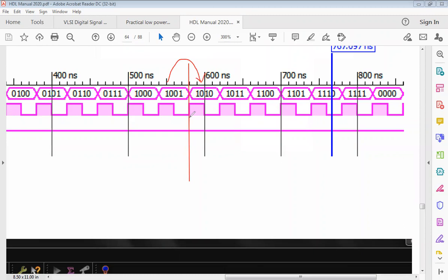So this is happening when the clock is actually high, so which means it is increasing, it is rising edge, and the value of reset is 0. Okay, if the reset is high, then what happens? Whatever count is here, that becomes 0. So this will keep counting on and on. See, it came to 1 1 1, and then later it will just go to 0. Why? Because we have taken a 4-bit value, right? So maximum it is going to count between 0 0 and 1 1, and then from 1 1 to 0 0, right? So this is how it happens.